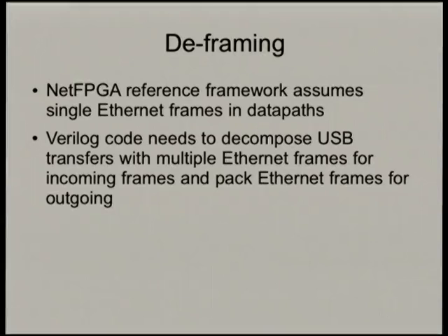The other thing that the Verilog code needs to do is to deframe. We can have up to 90 odd Ethernet frames packed into one USB 2 transfer, and they need to be deframed once they hit the FPGA, because the FPGA is only dealing with Ethernet frames.